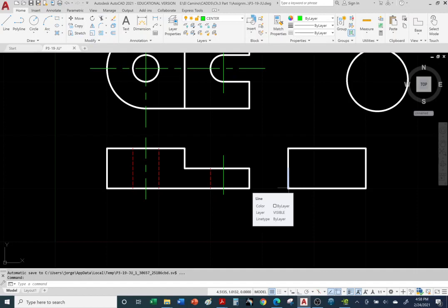And as I mentioned before, maybe I didn't mention it in a previous video, but if you're working on an aircraft, for example, if you're working on the fuselage, typically the world coordinate system or the universal coordinate system is towards the front of the fuselage. It may be at the nose of the fuselage, or the front towards the landing gear, or it may even be at the firewall that separates the engine bay from the cockpit.